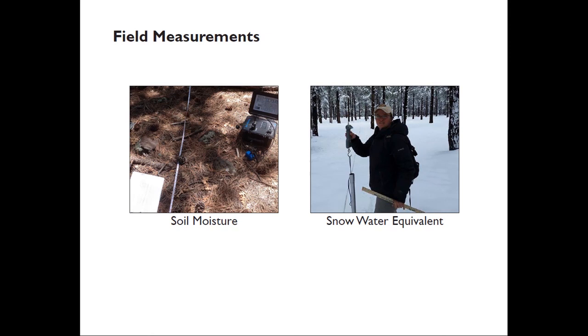At a couple of sites, we also did have continuously recording soil moisture probes, just to give us the full temporal element. At all of the sites where we had one of these probes, we were also taking snow water equivalent measurements. And we did this as best we could, transport allowing in the winter, but we're generally able to get some data from immediately after large snowstorms and then a week or so after. Things melt pretty quickly in Flagstaff. Normally we'll get a big snowpack, a foot or two, and then it'll be gone in 2 or